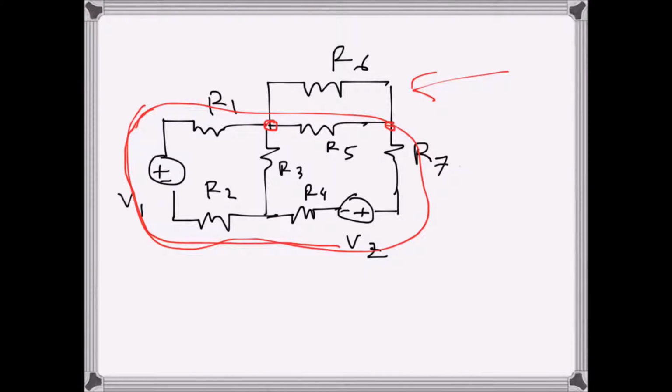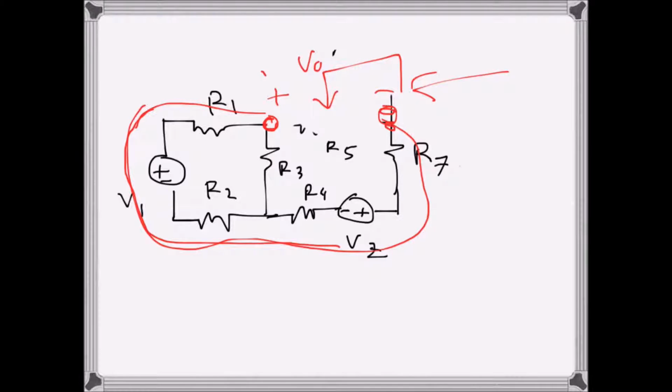So basically what has to be done here is R5 and R6 are taken away, so this remains as an open circuit here. Once we do that, because we want to replace this part, we have disconnected the circuit at this point, and we will find the open circuit voltage here. Let's say this one, VOC, and that will be the Thevenin's voltage.